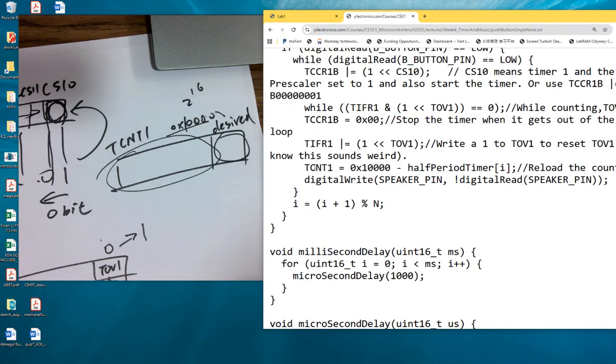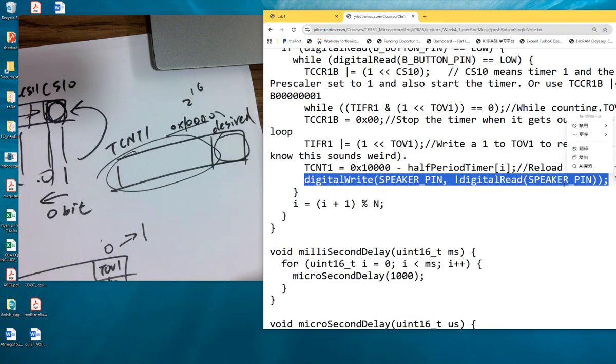So now I got that defined, and then I flip that pin. That flip is just one little part of the oscillation. So what is that part? Remember? That's a half period of the oscillation, right? Timer, flip. Timer is up, flip. Timer is up, flip. So you keep doing that to generate that oscillation. Make sense?